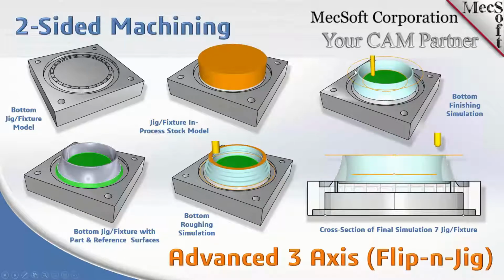You'll see that it machined it, looks really nice on the inside. It's got an area here that helps guide the tool past this edge here. And if you look at the cross section here, you'll see the edges here on this point and the edges on the inside. Those are all maintained during the machining process. And also this particular fixture has a chamber on the bottom, which allows the vacuum to be pulled through the fixture and hold the part down during machining.